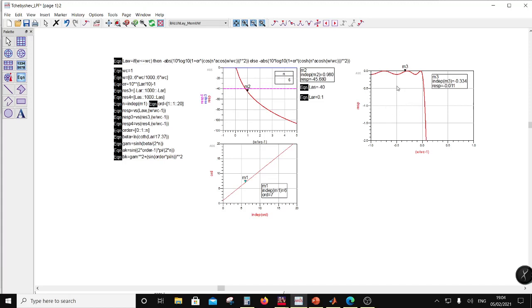If there is a dielectric, in this case borosilicate with a tan delta of 0.0023, and then there is a conductor of certain width, there are going to be losses per section, and as many sections as there are, that much loss there would be. So this whole ripple which you see here as 0.1 dB would be the insertion loss plus 0.1 dB ripple. That will be the total insertion loss which you will see in this filter.